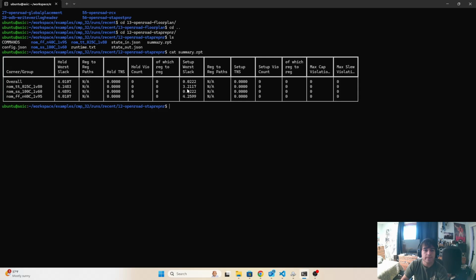You can think of the slack as being in nanoseconds. So this is kind of telling you we could increase the clock by 4 and it would be okay, roughly. Sometimes that's not true, but you'll have to learn that as we go. So that was the pre-place and route.